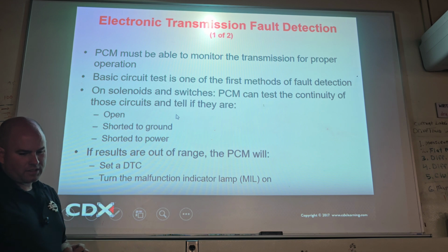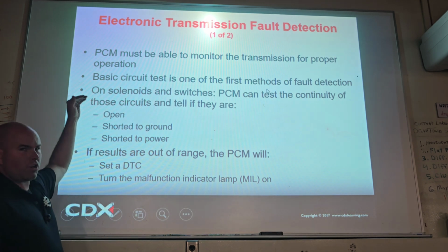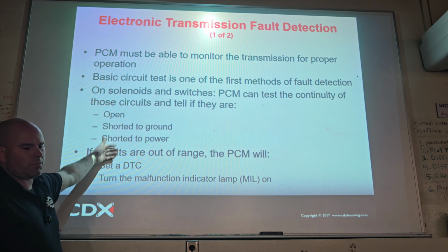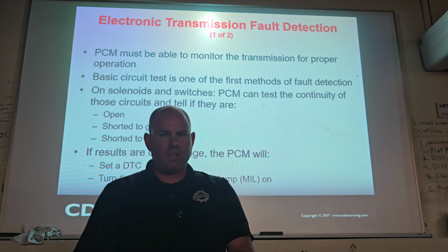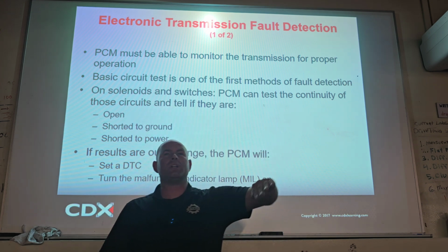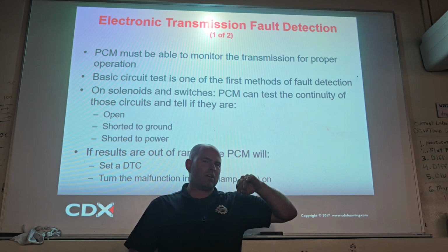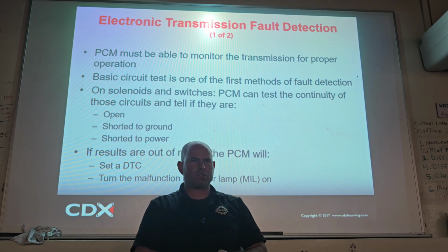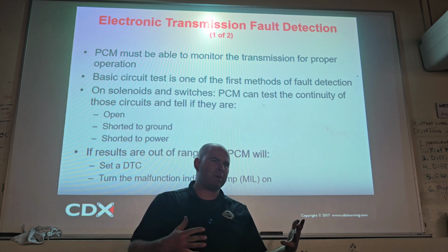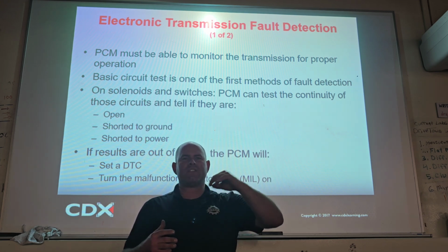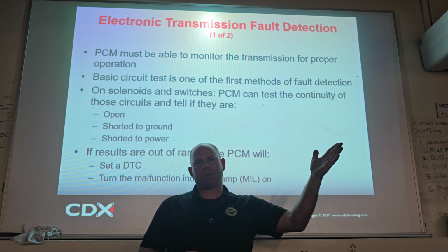That's all happening in the ECM. And then again, if it's detecting a fault, there will be an action. So you get a customer car, the customer may say, my concern is it bangs going into reverse. Well, it may only be banging going into reverse because it's in some sort of protection mode, right? Have you guys had cars with transmission fluid temperature faults? Transmission fluid temperature faults made a bang in reverse. Did you expect it to? I don't know. But as a fail-safe, it will. It'll say, I don't know what the transmission fluid temperature is, so therefore, max line pressure.